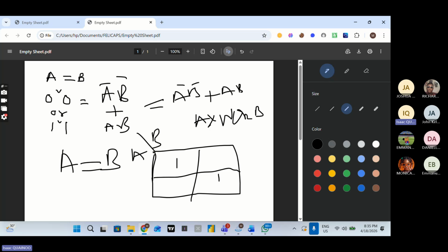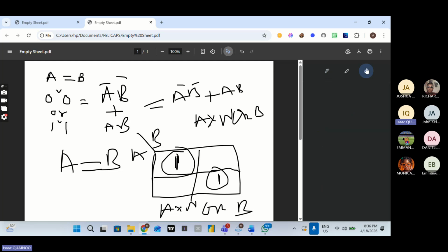So I was explaining the last time we were doing, I think, full adder, half adder, that there's a general rule that if you have your ones aligned diagonally, such that you can't select them together or minimize any further, it means the resultant expression is going to be the XNOR of your inputs, which is A and B. And that is the same as the equality rule.